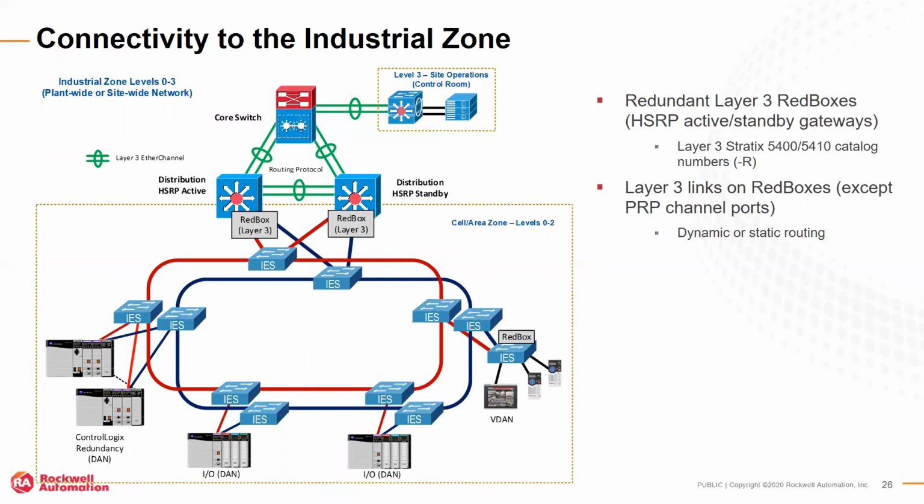But what is the scope is how you apply a Parallel Redundancy Protocol architecture to the larger plant-wide Ethernet structure. This example shows the correct way to connect a PRP to a CPwE system. In this example it is a dual ring for simplicity, but you would connect the PRP directly to a set of distribution switches.